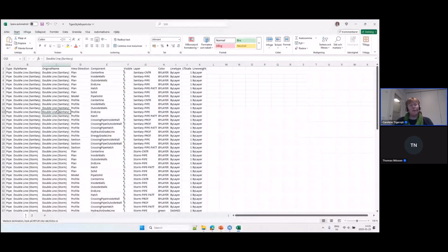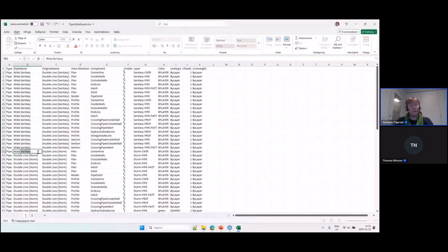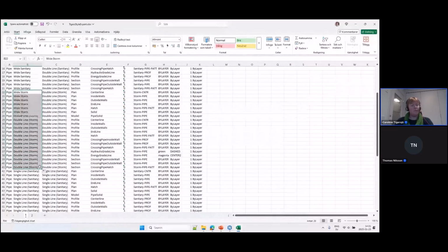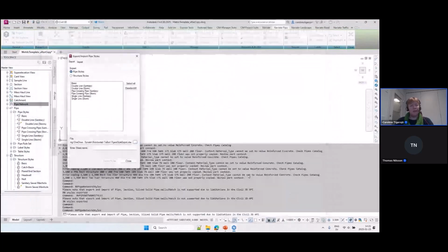Now, we can also use this to copy styles. So I want to keep the old ones, but I want to make sure that I create a new one. So we have original name here. That's my original name. And then I can do a new name here. So I can say that my new one should be wide sanitary. If you need to have a new one we can rename as well, but in this case, I'm just going to copy it. So wide sanitary and wide storm. So I'm going to create a copy of these ones. I'm going to save this one, close it out, and then I'm just going to do cancel in there.